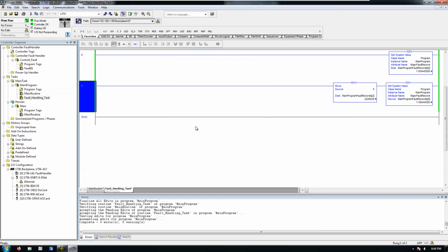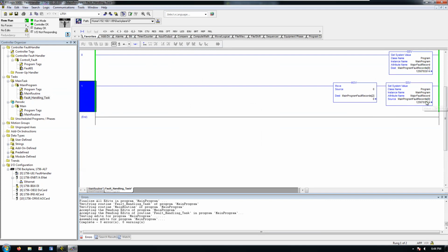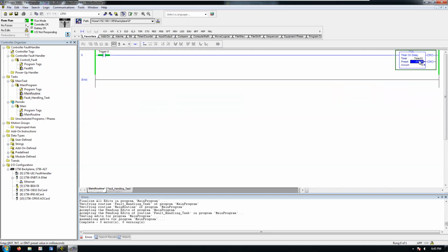So if we execute this code, this isn't happy because that value's bogus, but the code is constantly writing. So you can see we're still in run mode. So we know this condition was coming. This is a bad one to program around, but you could, let's say you haven't configured your HMI routine to limit what your set points are.